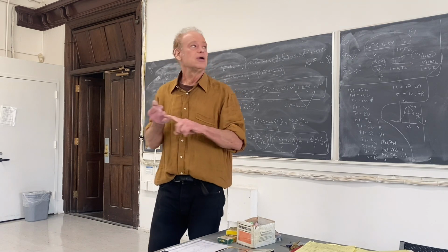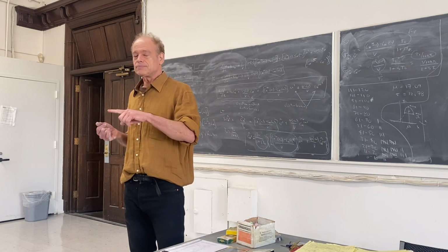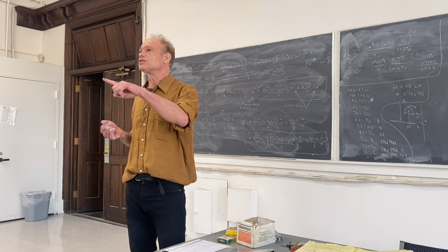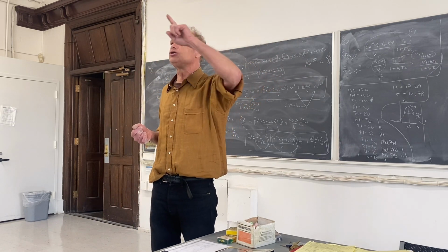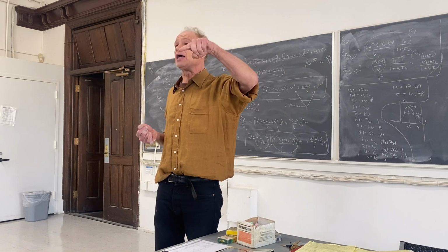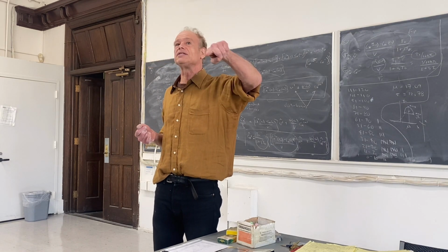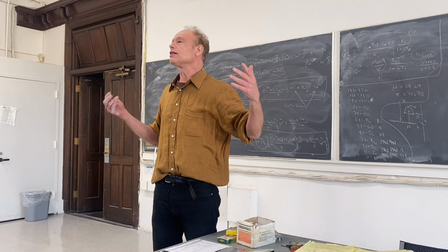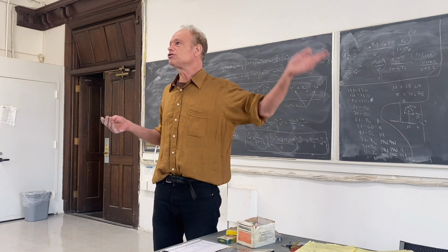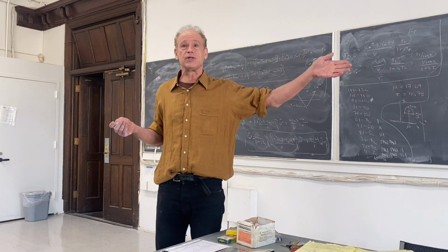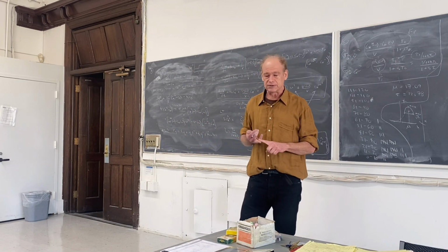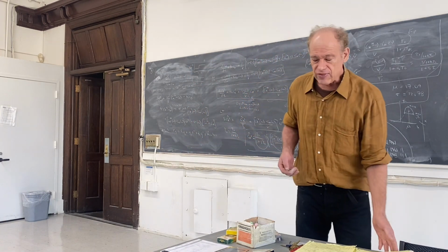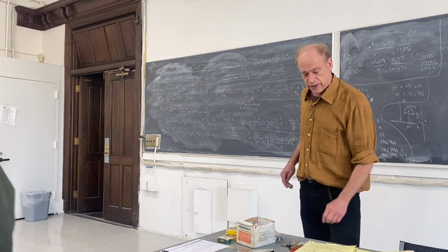Because once you do the partial fractions, you can evaluate just by factoring the denominator. Just by finding the zeros in the denominator and looking at them, you know all the issues of stability, which I had on the blackboard at the end of the last hour. And as you see, you'll also know the frequency response. So that's sort of the goal here of what we're doing.